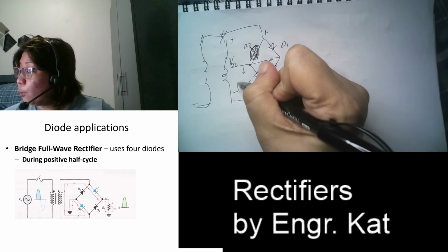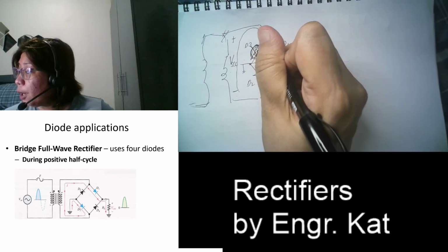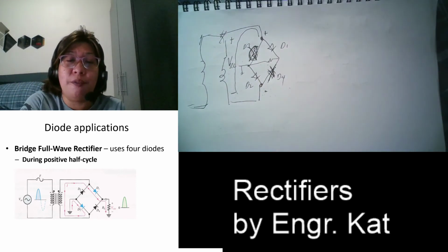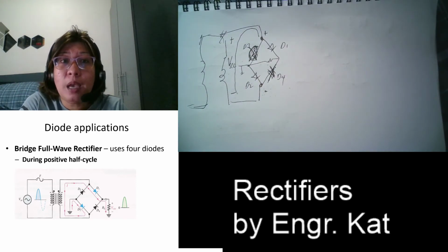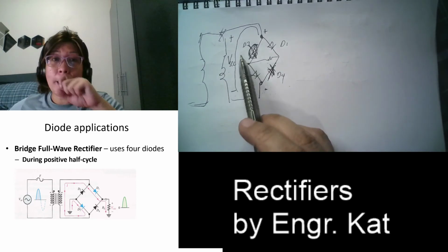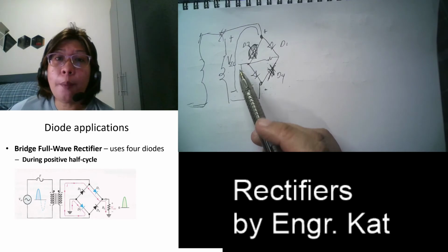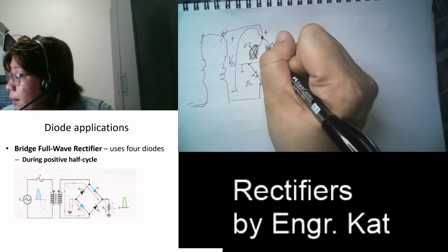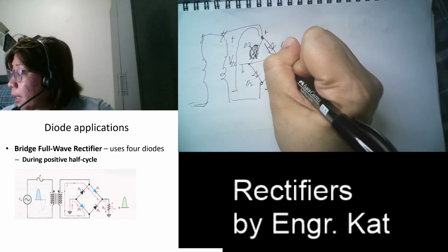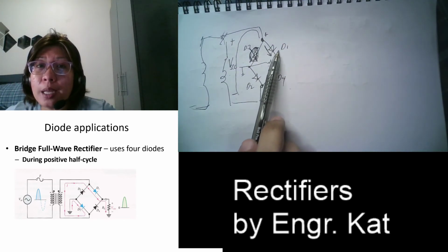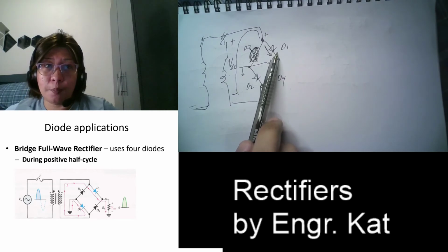At this junction, your current would divide, supposedly. However, this is open, so there is no other way for the current to go but to pass through your D1 in this direction. This is the same as the direction of your diode symbol.